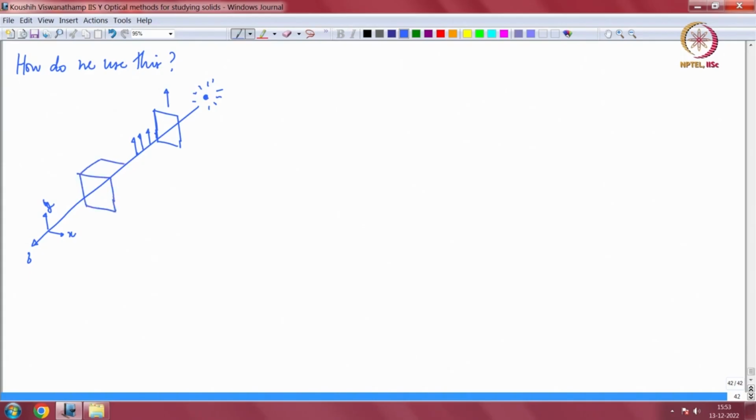And now I pass this light through a birefringent crystal. Again, we are not talking about stress optic birefringence, stress optic law and so on. I have not discussed any of that stuff yet, so the stress has not really come into the picture. The elastic part of photoelasticity has not yet been touched upon, but once you understand what goes on with a birefringent crystal, it is a simple enough thing to extend it to photoelastic materials.